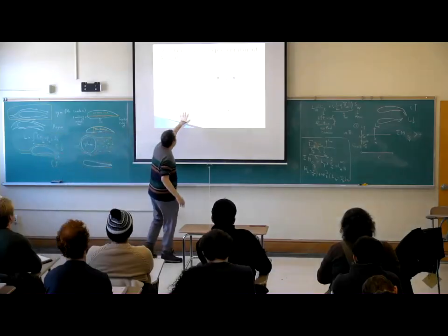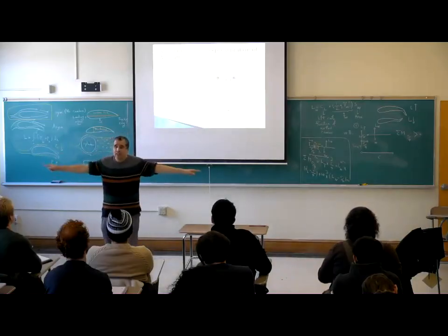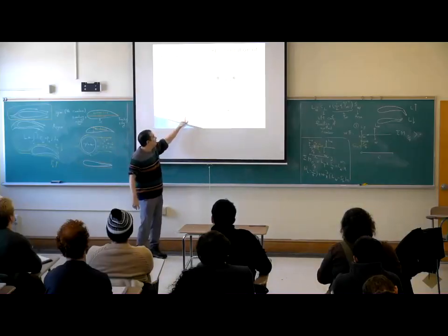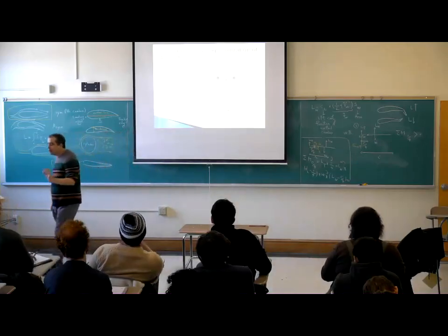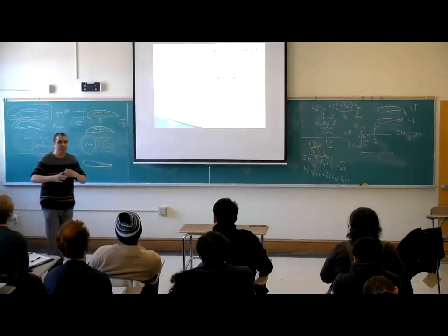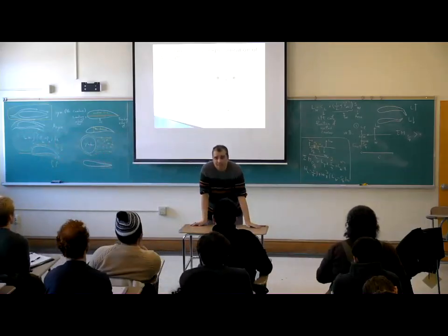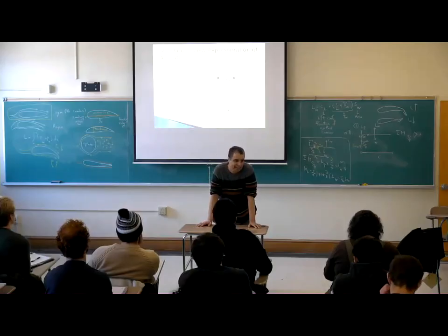You see the wings are not rectangular. The Wright brothers' wings were rectangular, but this is not rectangular. The chord here at the tip is much, much smaller than the chord at the root. The root is the place where the wing is fixed to the airplane. At the root, the wing has a higher length. At the tip, the wing has a shorter length.